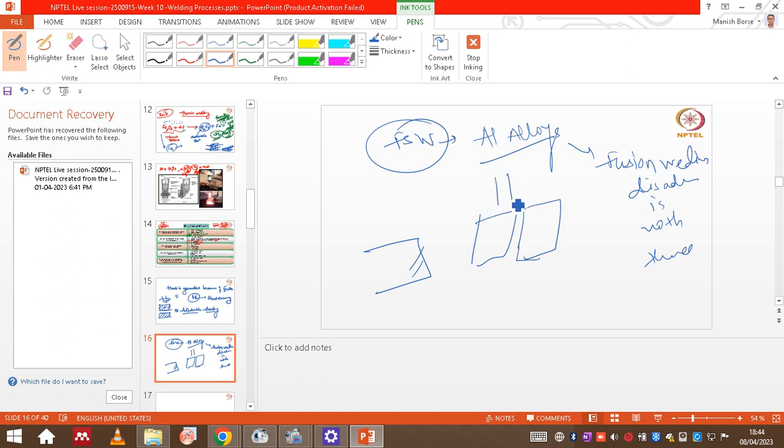then we have to use a certain external tool, right? And that tool is rotating, and that will create the friction at the interfaces, and heat will be generated at the interfaces, right? So obviously, the higher the rotation speed and the lower the travel speed, heat generation will be maximum, because the tool is confined to that particular localized region for more time, right? So heat generation will be maximum at that location. So the main heat generation is taking place with the help of some external tooling.